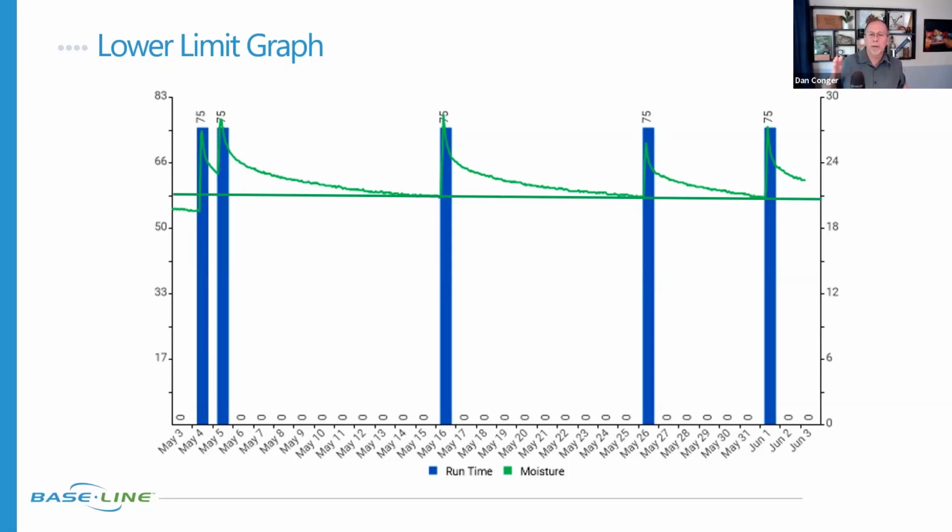Now, as we go later in the month, and we'll jump all the way to May 27th, you notice it watered again, but it was 5 days between waterings because it's later in the month. It was a little hotter. Beginning of May, it was cooler and needed less watering. It didn't take every opportunity; it needed to water. I just counted those day intervals. It went from 10 days in between to 9 days to 5 days. And that would be a sign of the ET rate increasing with the onset of summer.